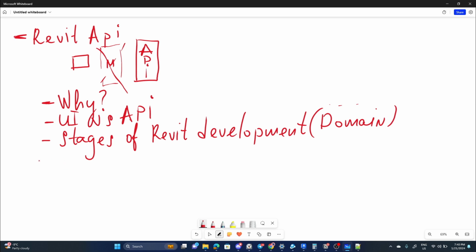Also, you'll understand basic object-oriented programming skills. Therefore, you'll be able to read the Revit API docs, navigate through them, and read their information. You'll also learn how to read information from Revit elements, not via code, but by using some tools that allow you to investigate and explore what they contain behind the scenes.